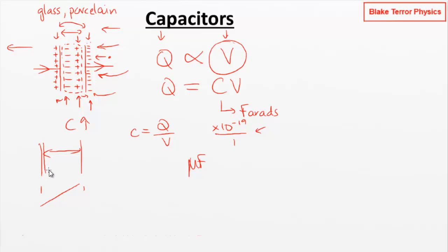So that can help. And then a bigger dielectric in there will insulate better against the effect of the large potential difference. So you want to physically make the capacitor bigger with a larger lump of dielectric between the plates in order to protect against very high voltages.